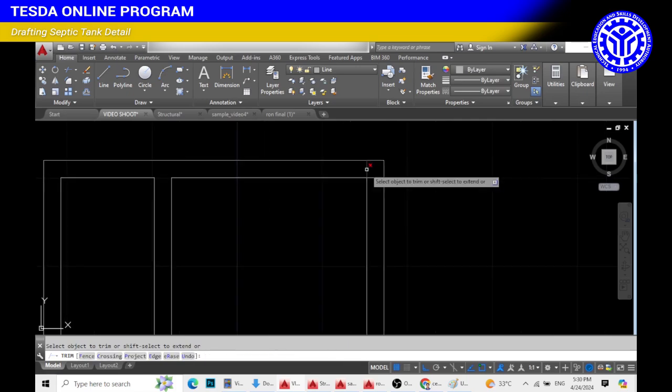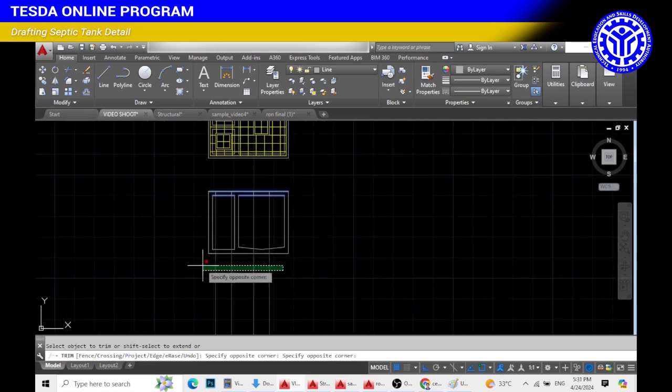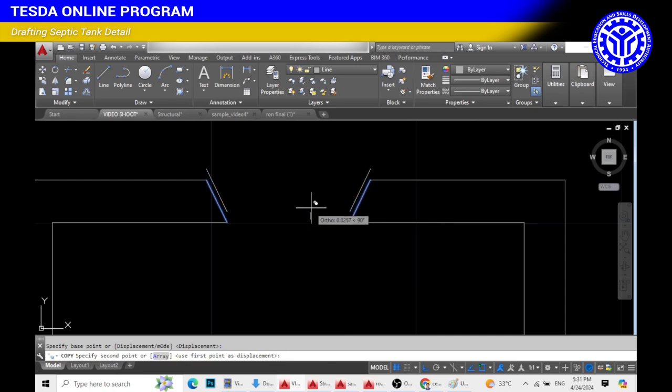Trim unnecessary lines. Project construction lines for the manhole. Trim unnecessary lines. Stretch the manhole cover by 0.05 to create an incline. Trim unnecessary lines. Copy the lines to create a removable manhole.